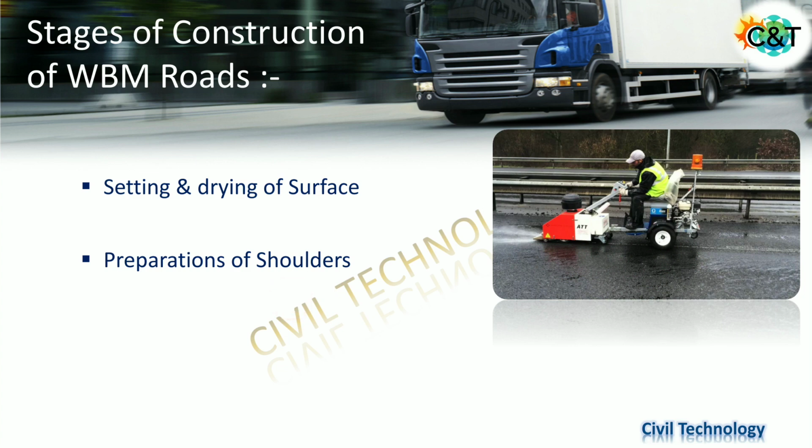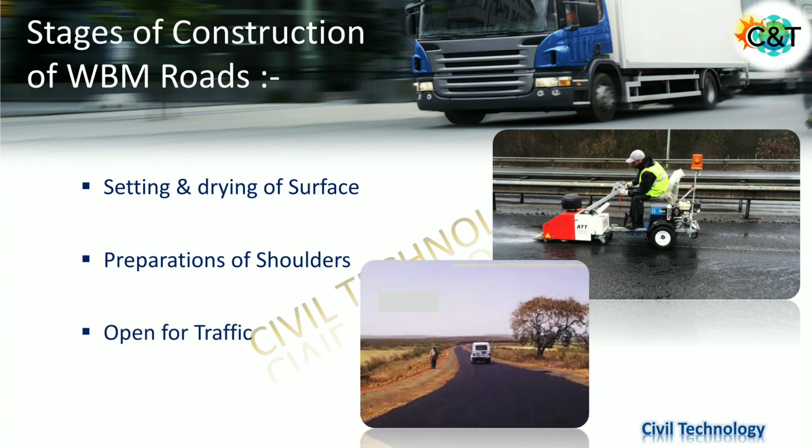At the time of curing we simultaneously construct the shoulder along the side of the road, whatever material you use, be it a bituminous material or an earthen shoulder you have to prepare. Accordingly you can prepare the shoulder simultaneously. There is no worry about it. And lastly, if we see all is good, everything is proper, no depressions or voids are present, we open the road for traffic, and for a few days the traffic should be well distributed over the entire length of the road. So this is all about the steps involved in the construction of WBM road.